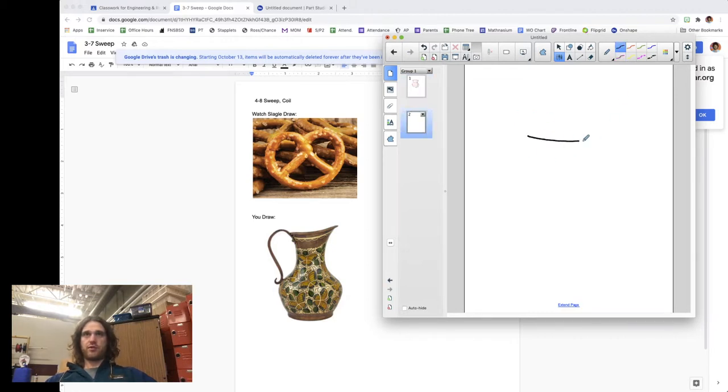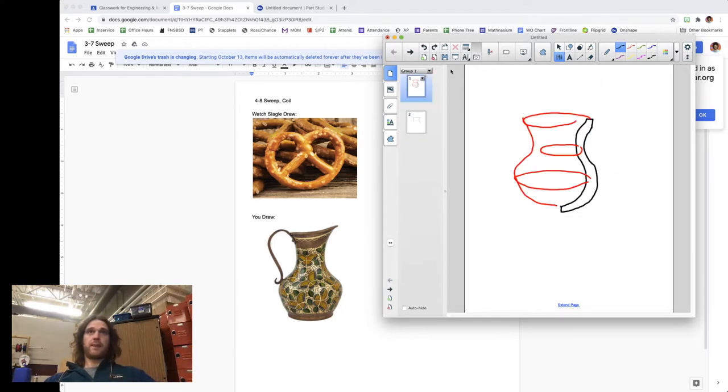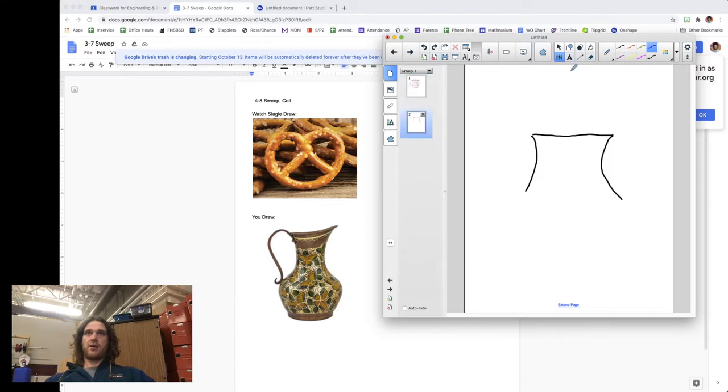So then what you're going to do is at that top cross section, if I'm just looking from the side of my picture like this, and this is what I see, I'm going to create a sketch in whatever the front or the right plane, whichever one you selected. That's the plane that's cutting this down the middle, right? Because you should be spinning it around. You have a plane that's slicing it down the middle. You're going to create a sketch on there, and what that sketch is going to look like is a shape that looks like this. You're circling that out, and actually it looks a little bent. So it's going to be more like this.